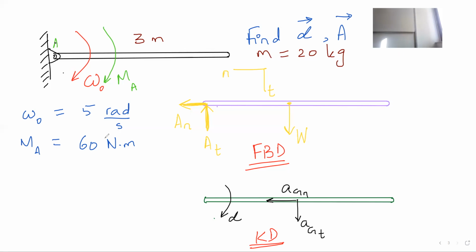Now what you have to understand is that this is not a strength of materials class anymore. Strength of materials is very statics based, right? Those problems are static. This is not a static problem. This is a dynamic problem. So you cannot just say, well, the reaction in the x direction is zero. No, it's not zero. It cannot be zero because when the object is rotating like this, there would be a normal acceleration component as well.